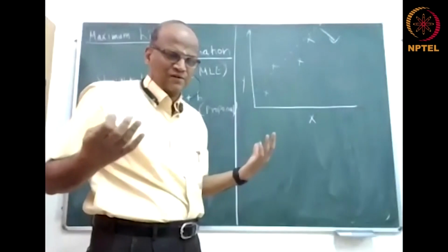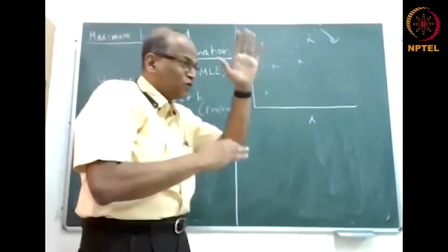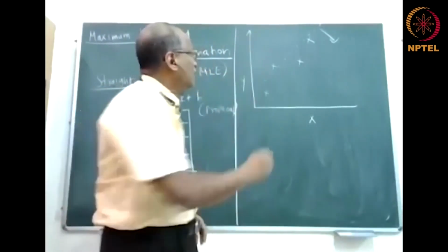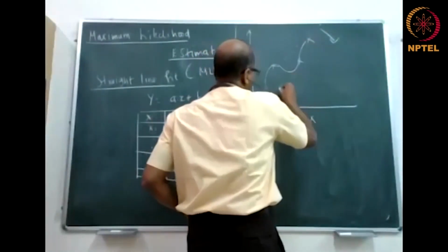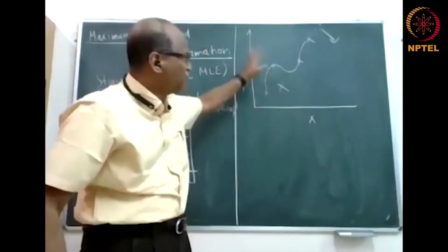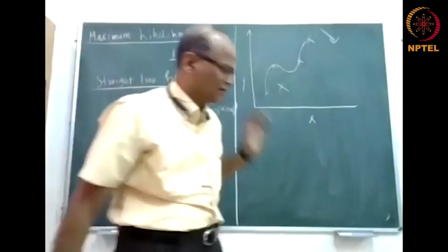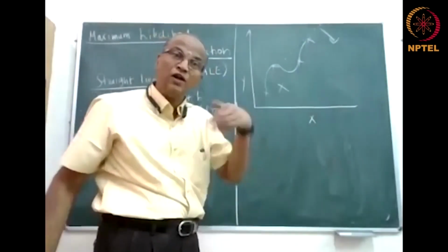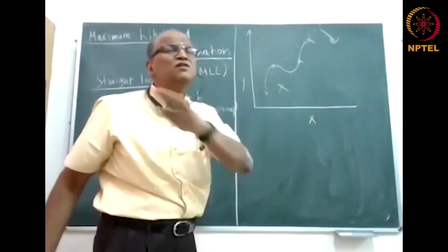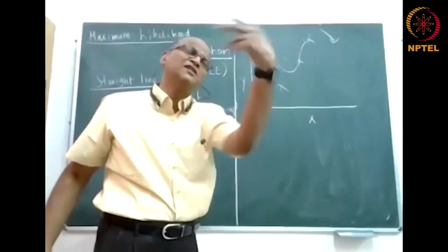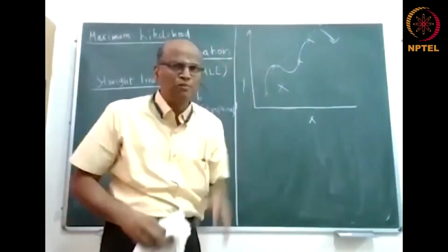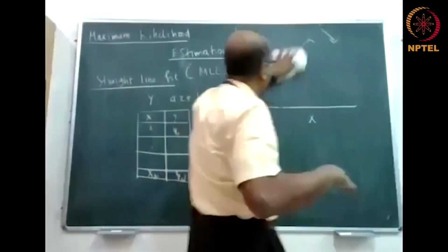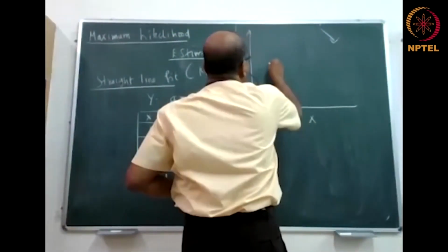So you don't know the statistics, but you know that you're trying to get one line because you know that the solution is a line. It's not a curve or polynomial. So if you do like this, it's absolutely wrong. You don't know any heat transfer. Temperature will never vary like this in nature, because the thermal conductivity would have to have a tortuous variation, K equal to ax plus b, then cx plus d. There is no such material because it is against common sense. Mathematics can say so many things. It is mathematically possible, but mathematics is not life. Reality is different. So we should not do that.